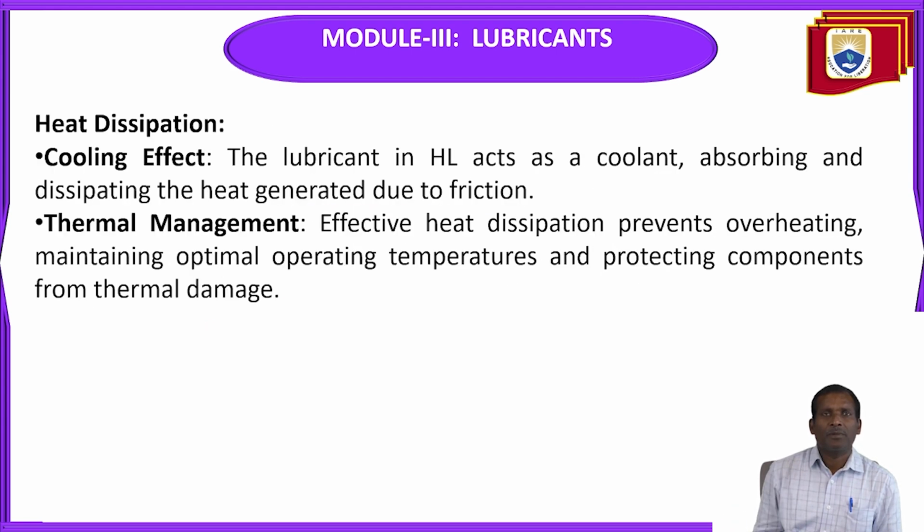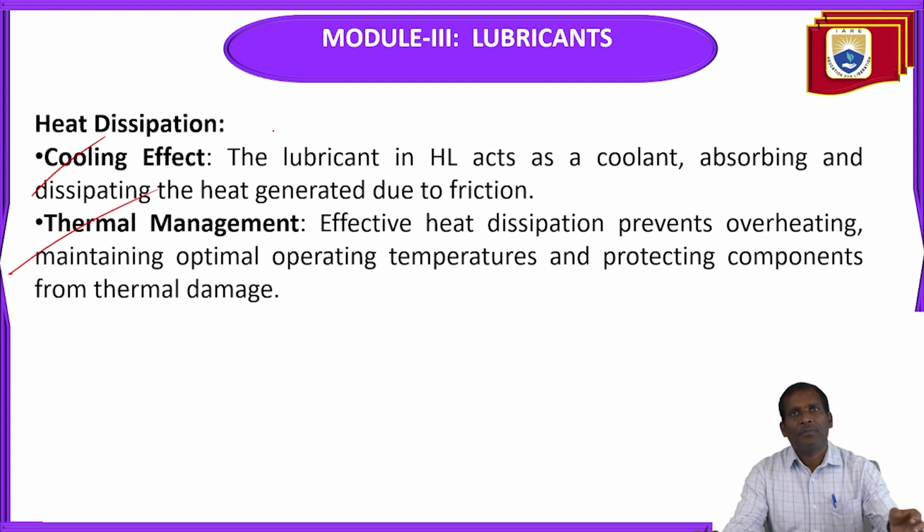Next, heat dissipation: cooling effect and thermal management. The lubricant in hydrodynamic lubrication acts as a coolant, absorbing and dissipating the heat generated due to friction. Effective heat dissipation prevents overheating, maintains optimal operating temperatures, and protects components from thermal damage.